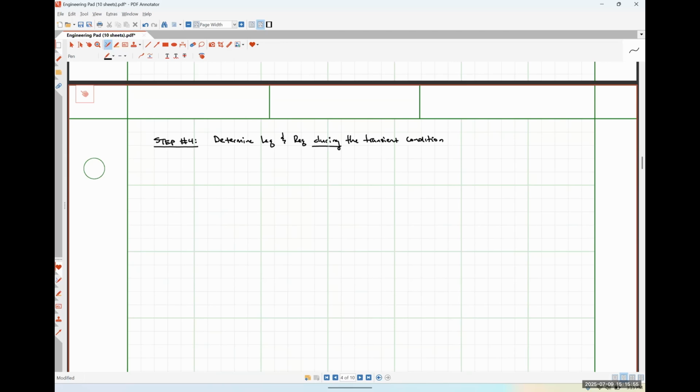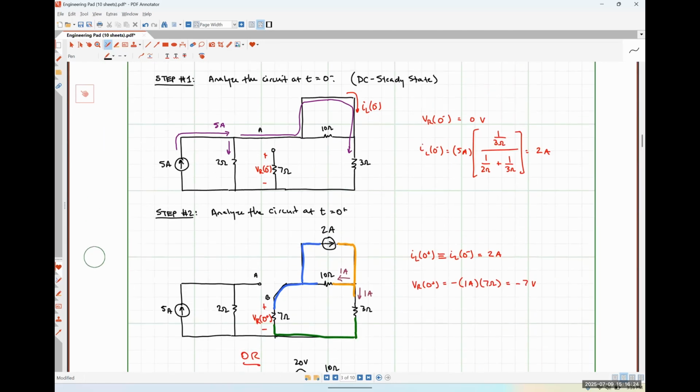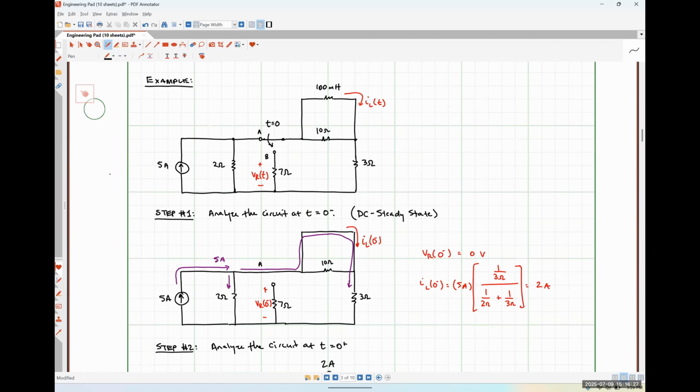So generally speaking, I'm only going to give you circuits that have one resistance and then multiple energy storage elements that can be combined, or one energy storage element and multiple resistances that can be combined, so that we can generate a pretty straightforward methodology for determining the REQ and the LEQ or CEQ for our systems. So I want to scroll back up and look at our original circuit. Our original circuit only has a single inductor. So I'd love for you guys to take a crack at what you think LEQ is going to be.